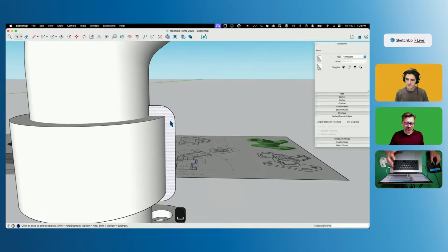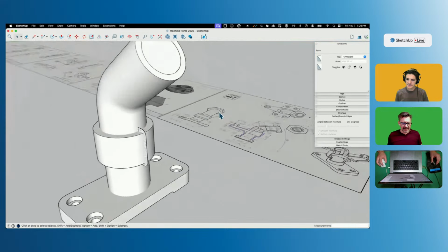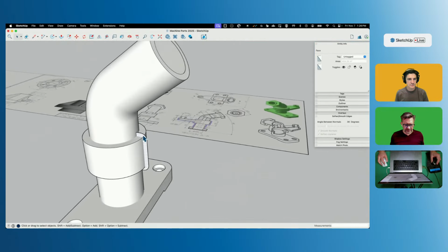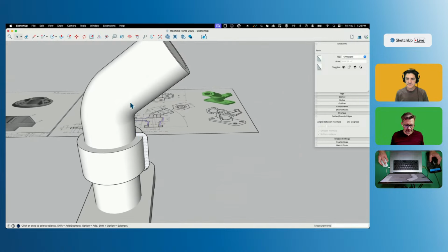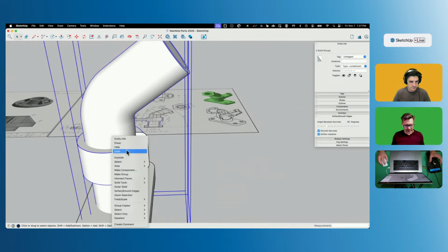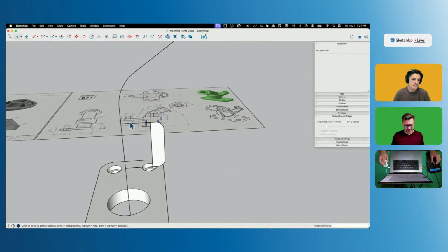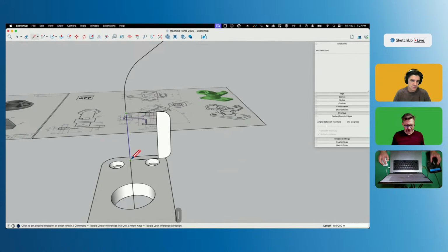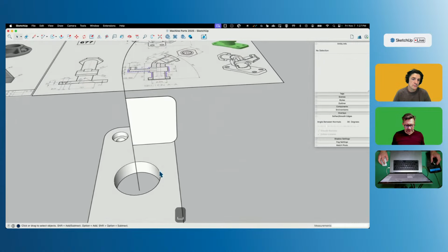All right, now this shape I can extrude around. Actually, you know what? Here's what I'm going to do. I'm going to hide all of this again temporarily. And I'm going to make this a little bit bigger because I want to make it more. And then I'll just put a new circle in. A new circle right here. 48 sides. Yes. And I can just say, follow me with this.